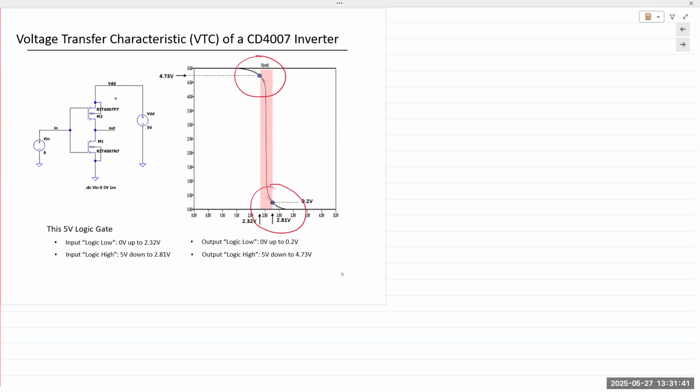It's never going to be a perfect square wave, right? Devices can never transition from 0 to high in an instant, nor go from high to low in an instant. There's always a switching time. There's always a transition time between logic 0 and logic high. And all of these affect the design of your circuit. Oftentimes when you perform procedures in the lab, some lab groups have some issues depending on the fabrication of the device.